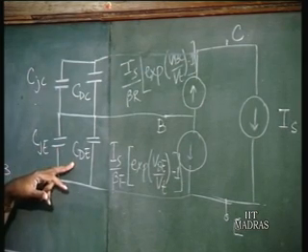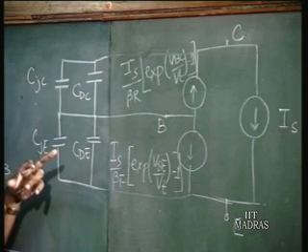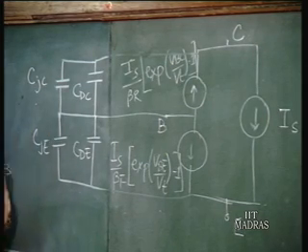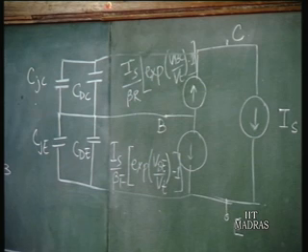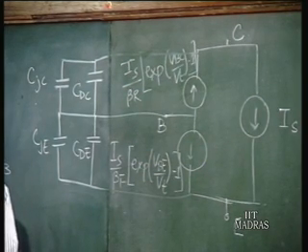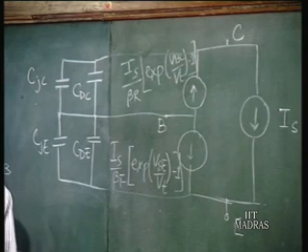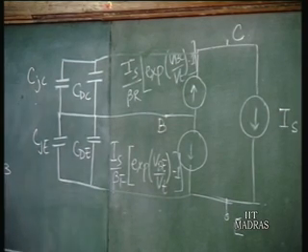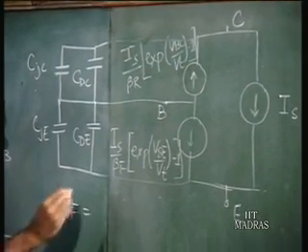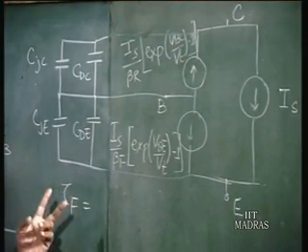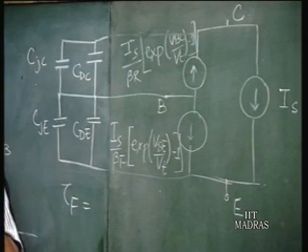For the diffusion capacitances, they are again related to the transit times. So in a bipolar junction transistor, you have two transit times which are defined. One is called the forward transit time, and the other is called the reverse transit time. What is the transit time? The transit time, as we have defined it, is the ratio of the charge stored to the current. In the forward transit time, all the forward parameters are defined for VBC equal to 0.